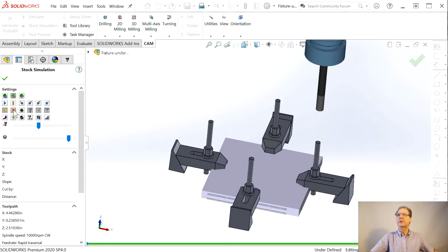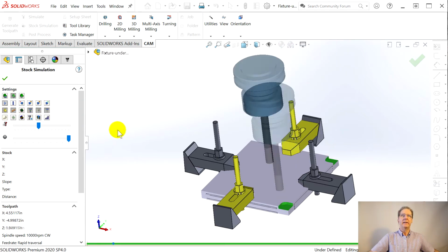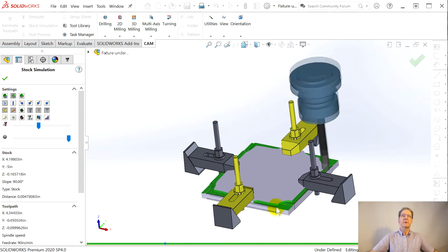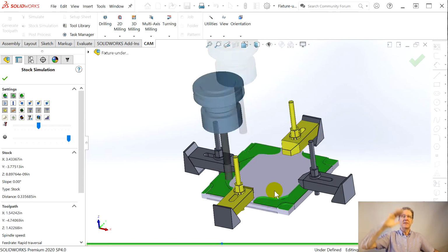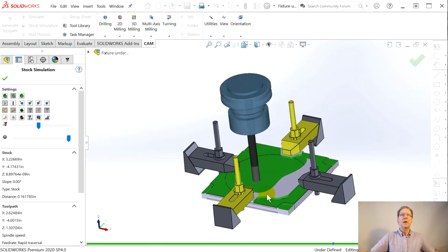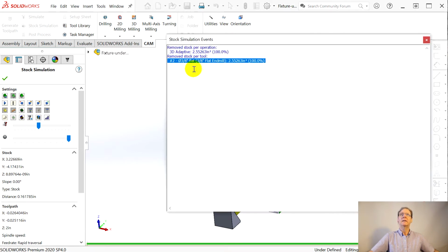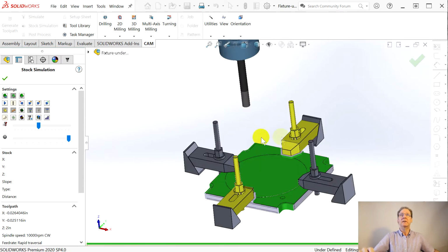And we can turn on here because, see, we haven't lit up both operations. We haven't lit up both setups when we asked to simulate. We're only simulating the first operation. So when you turn this on, it turns this on. And this is how, bless their heart, when the holder hits this bolt, it will tell you. Okay, so you go here, and I still haven't figured out how not to do the corners. When I say just go from top of stock to top of part, it doesn't, it reds out and refuses. But when the little happy ending thing comes up in a second here. Okay, so since there's no clashes listed here, my tool never turns red, sorry.